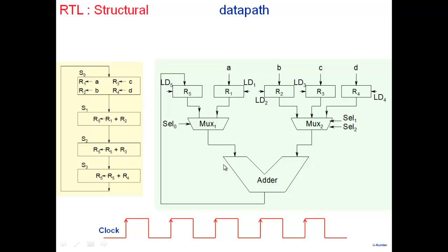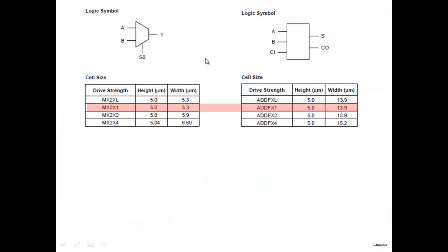Now, before that, note that we said that we all wanted to use 1 adder. But then there's a price that you have to pay. If you use 1 adder and it's shared amongst the different registers, you have to introduce muxes to this thing. So there's a price that you have to pay. Why are we willing to pay that particular price? Well, you can see here. This is a 2:1 mux, just 2 bits here and a select input.